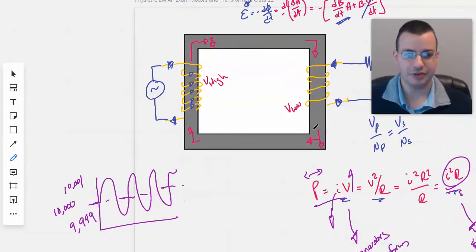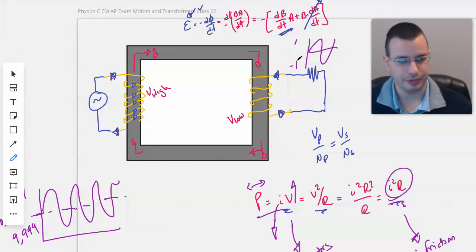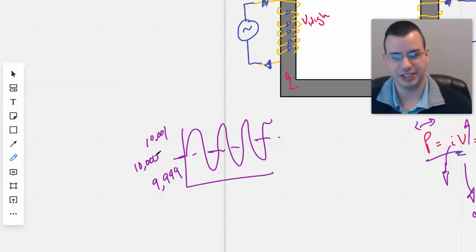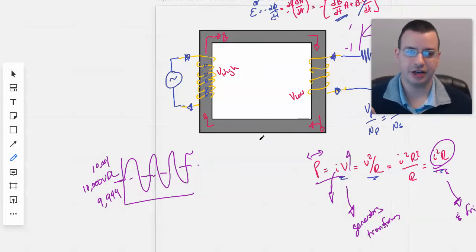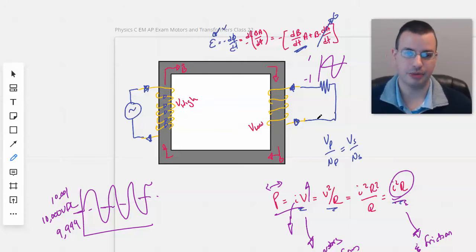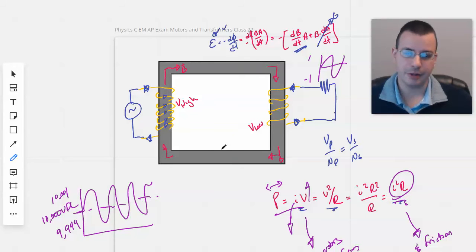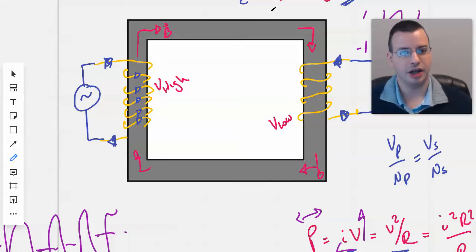And so the idea is if you want to isolate it over to this side, then this would just be from 1 to -1, because this extra 10,000 volts DC over here would be filtered out, more or less. You can isolate your circuit from DC current, or DC voltage, because it doesn't alternate, it doesn't fluctuate.